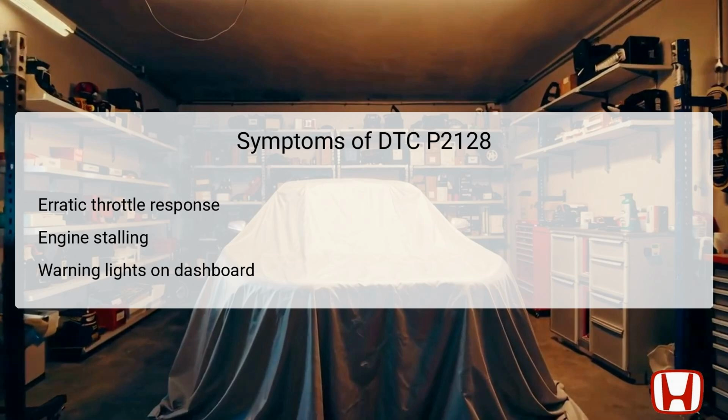Another potential symptom is engine stalling, as the engine management system may struggle to correctly interpret the accelerator position. Additionally, drivers may observe warning lights on the dashboard, specifically the check engine light, indicating a fault within the engine management system. Recognizing these symptoms promptly can aid in addressing the issue before it escalates into more serious vehicle performance problems.